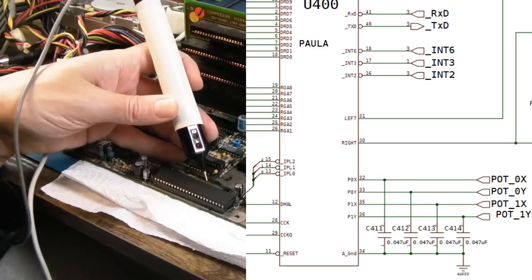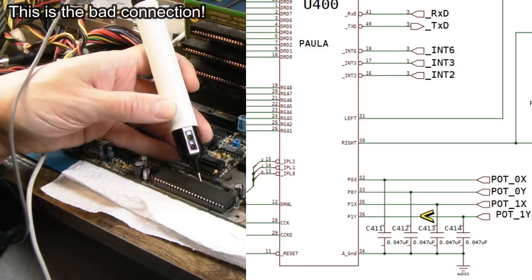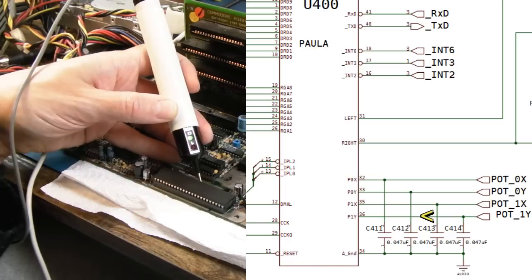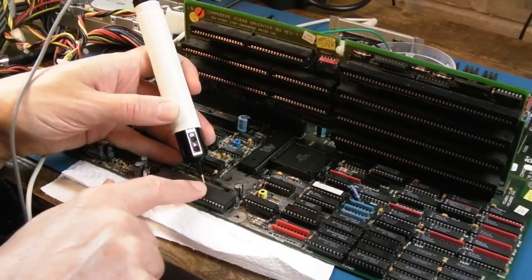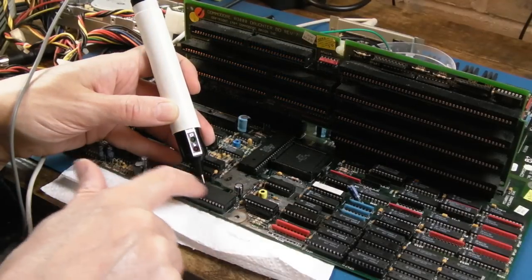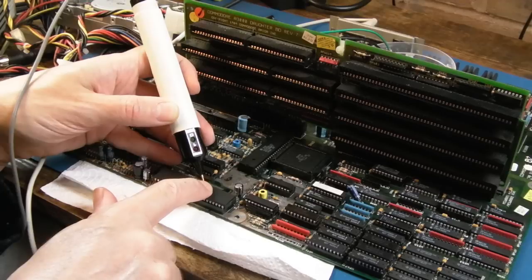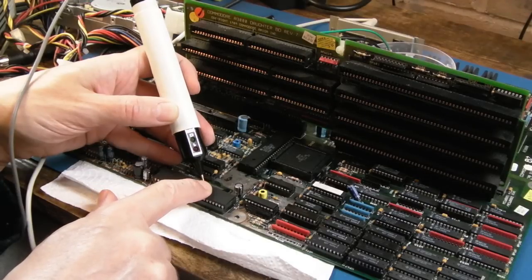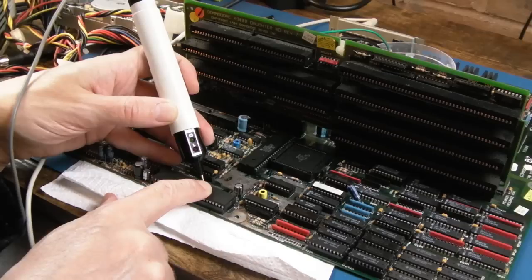And we've got a pin that's not used, and then we've got a floating connection here, mouse not doing anything, and then this is the final of the pot X, pot Y. Now the right button on that port makes that toggle, but the very fact that the connection there is floating, I think that is the issue. I think this is not receiving a connection. So I did suspect one of the pot X, pot Ys were not right round here. It just took me ages to work out how on earth the buttons are actually processed on this. I always thought it was the CIAs. I'm getting confused with the C64 fire button, I think. Yeah, the CIAs don't do it.